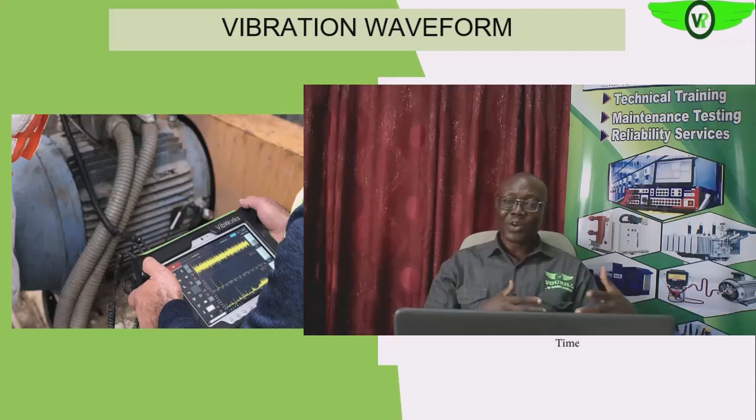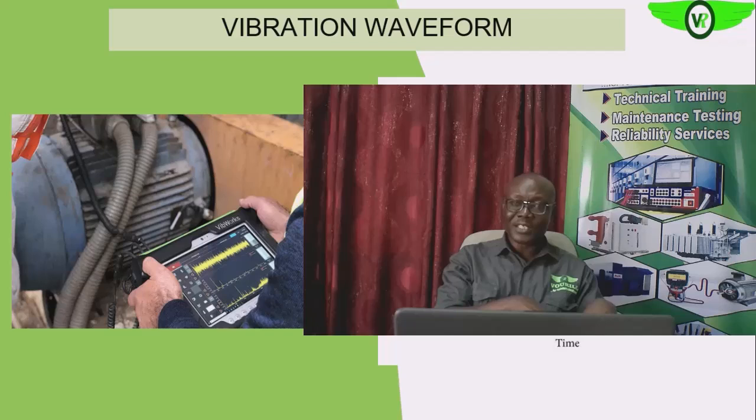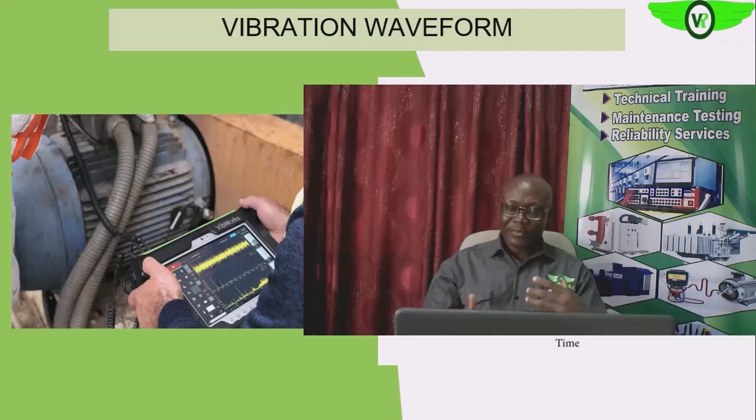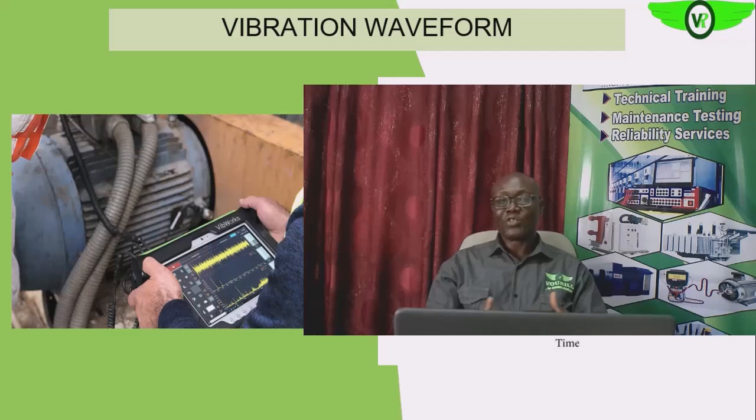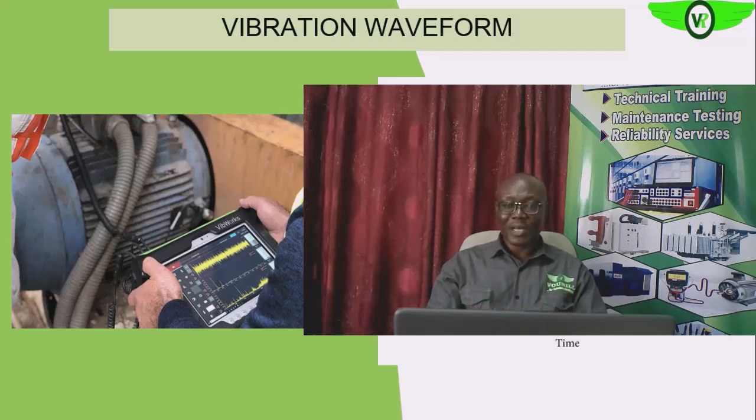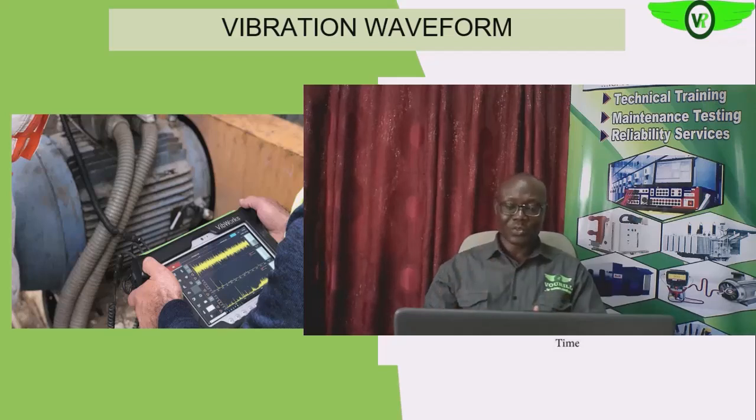So as situations are developing negatively around the bearing, around the rotor, around the impeller, you'll be seeing them. And if it goes beyond the level that you feel could be tolerated, then you can flag off the alarm so that what needs to be done to bring the condition back to normal is done, so that the vibration levels will reduce again.